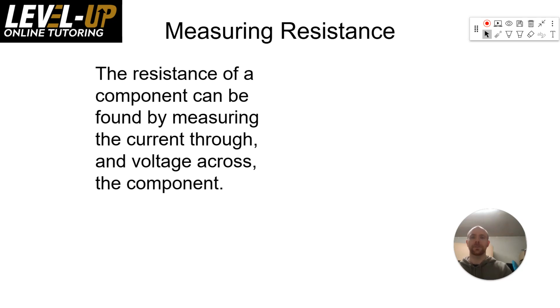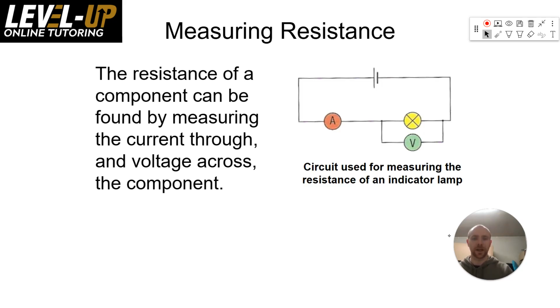We'll look at this in more detail next video as well, but how do we measure the resistance of devices? Well, this is a circuit diagram that you have to be completely familiar with. The number of exam questions that come up with this diagram is quite phenomenal. So what you're always going to be doing is, the device that you're trying to measure the resistance of is going to be in series with your voltage provider, whether that's a power pack or a battery.